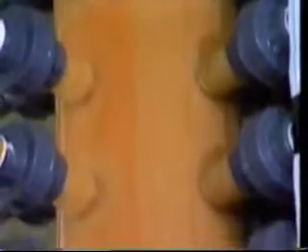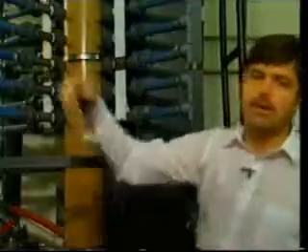We've oriented the model in a vertical position today and attempted to do a gravel pack that fills up both the annular space around the outside of the screen as well as the simulated perforations. We have 12 shots per foot of perforations on here, and when we experience a high rate of leak-off, as we did today, we can sometimes run into problems with the gravel placement in the annular space.